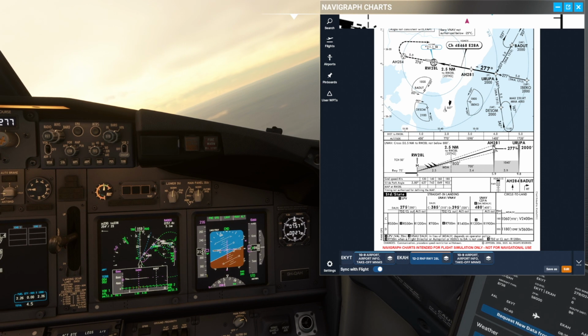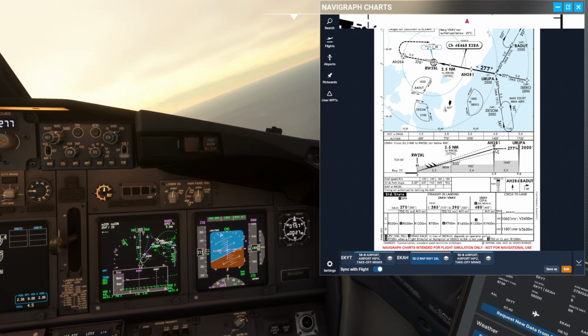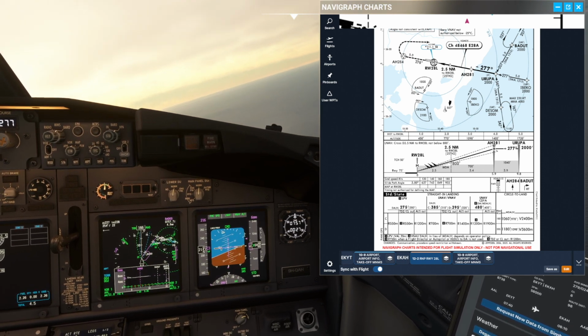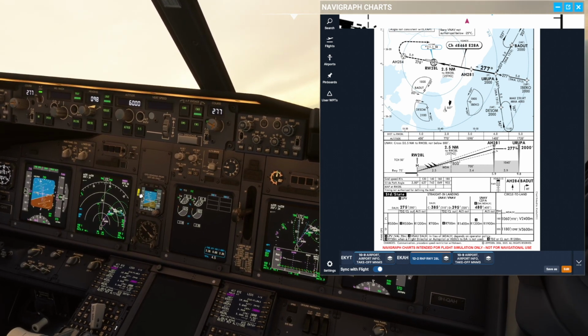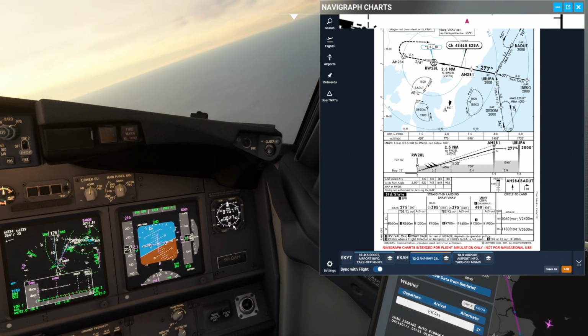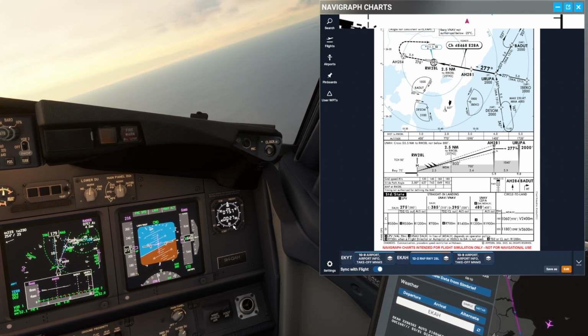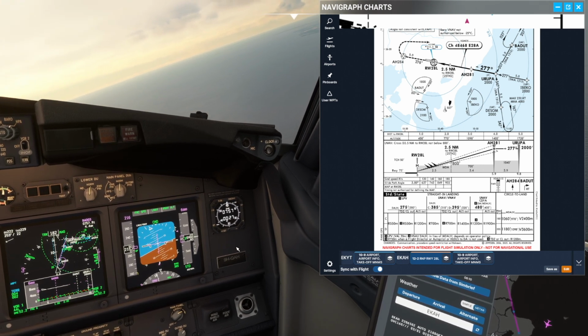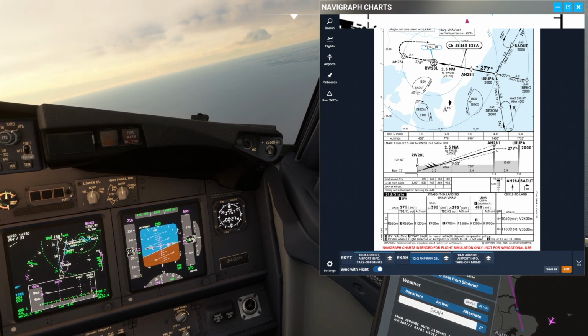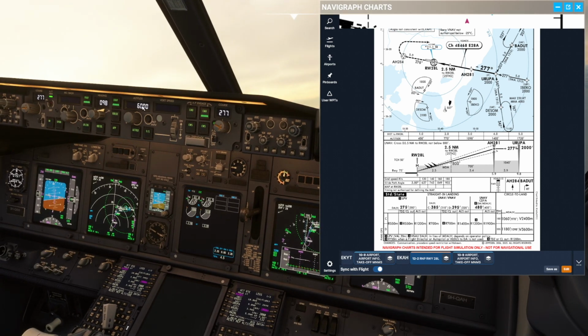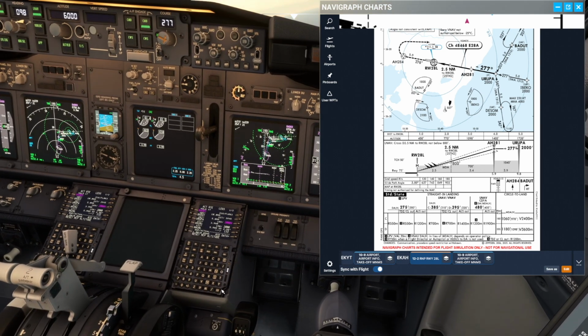And when we cross the final approach fix, I will call VOF altitude if we have any flags or if we have no flags on the altimeters. And then we're going to start our descent. At 1,000 feet above aerodrome elevation, which is going to be the start of the white bar, is the latest point at which I will recycle the MCP selected altitude to the missed approach altitude.